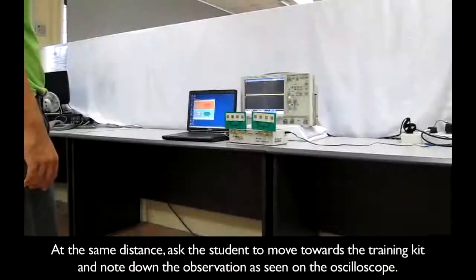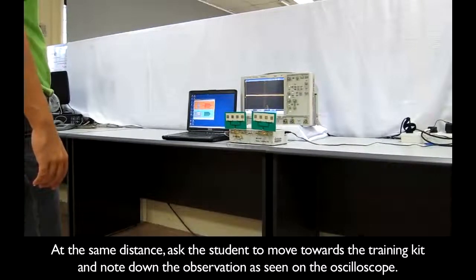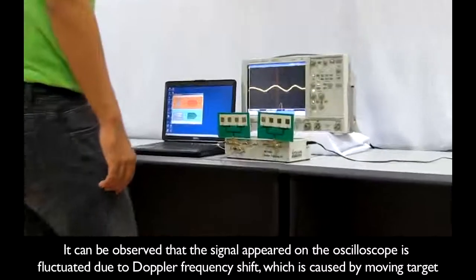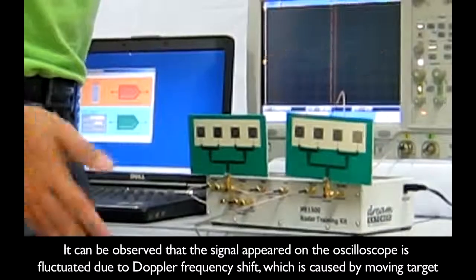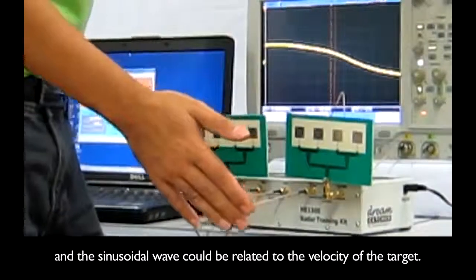At the same distance, ask the student to move towards the training kit and note down the observation as seen on the oscilloscope. It can be observed that the signal appearing on the oscilloscope fluctuates due to the Doppler frequency shift, which is caused by a moving target, and the sinusoidal wave could be related to the frequency of the target.